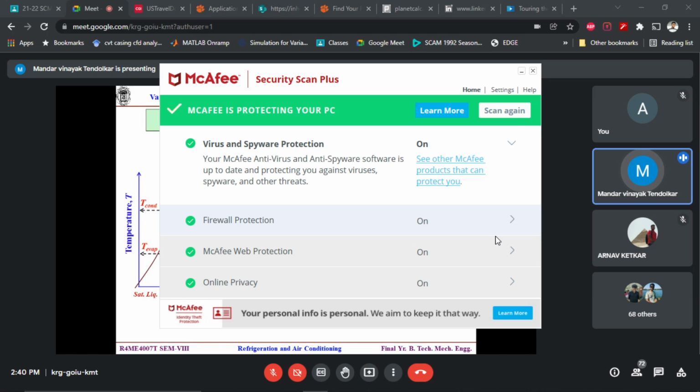In Carnot cycle, what we assume is an isentropic expansion. Here it is isenthalpic throttling. So process 3 to 4, which is slightly different than 3 to 4 dash, which would have been the isentropic one. Correct? Yes, sir. Yes or no?